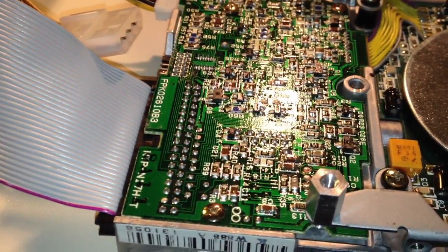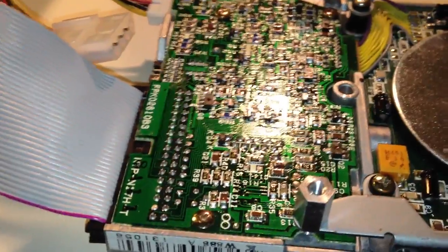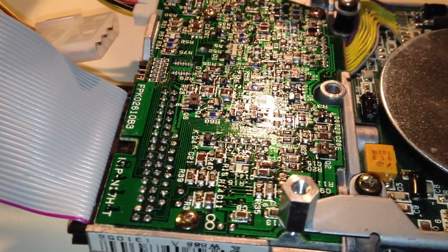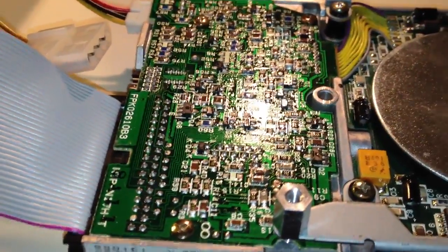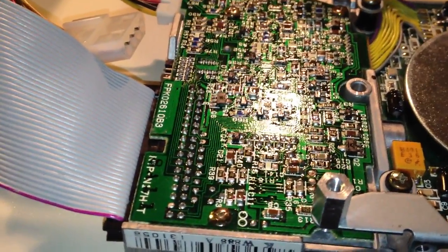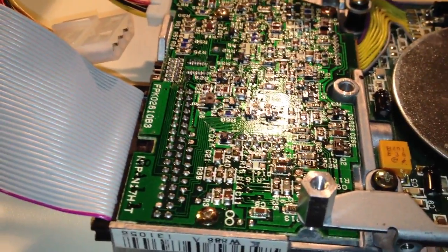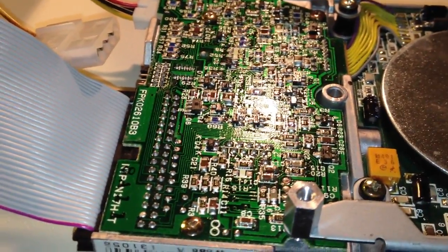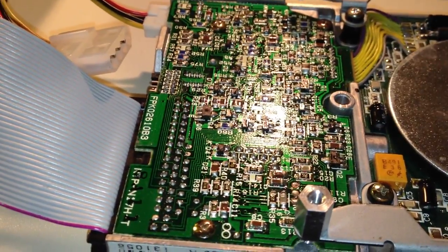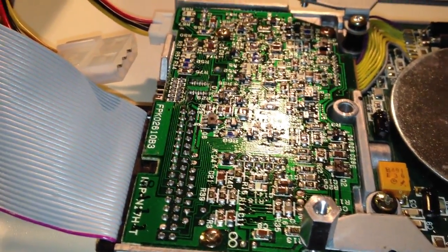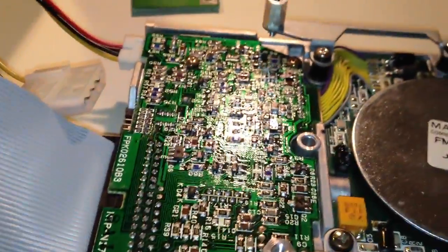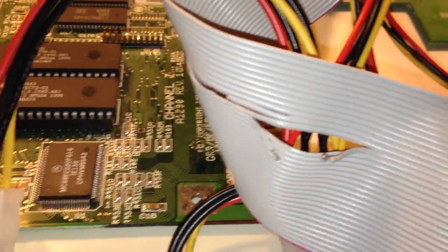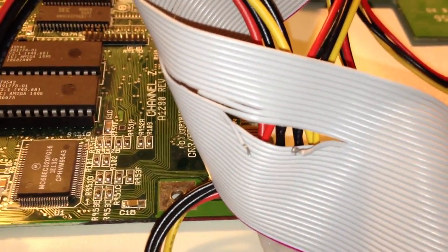So the problem that this person is experiencing with his Amiga is most likely due to a problem with either the incoming serial data, pin 22, or a problem with the gate signal, pin 24. Now, which one of those two signals might be causing this problem? So, let's try that out. Here, I have cut the signal for the serial data, the incoming serial data.